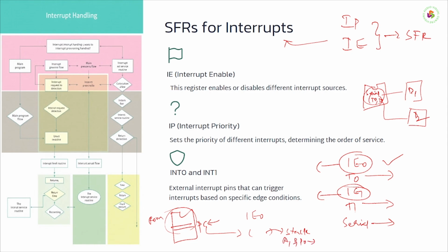All of these are also moved onto the stack. The program counter then changes its course from the main program to the interrupt. Every interrupt has a separate program stored in a location apart from the main program's location. Each such subprogram is called an ISR, interrupt service routine.